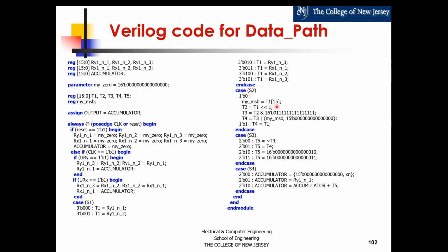Then I go down. The second block, if you remember, was either passing the signal, I'm calling that T4, and here I have T1 coming into it, or doing the shifting by 1 bit to the left. But this is an arithmetic shifting because I'm doing math here. So I have to jump through some hoops to do an arithmetic shift, which is keeping the sign bit.